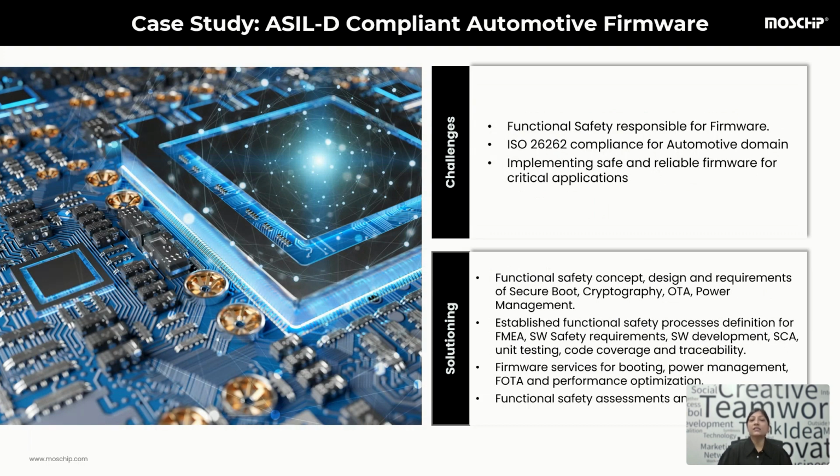This is another ASIL-D case study in which we developed automotive firmware for an SoC. It is fully aligned with functional safety and cybersecurity standards. The firmware included key features such as secure boot, encryption, OTA updates, and advanced power management. The main challenge was to balance the performance with stringent safety and security requirements within limited resources.